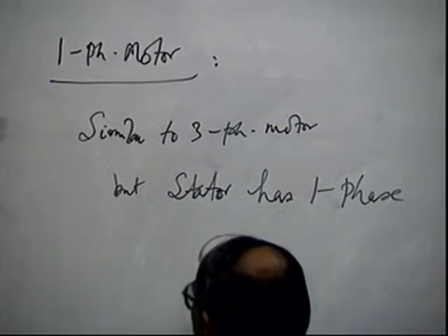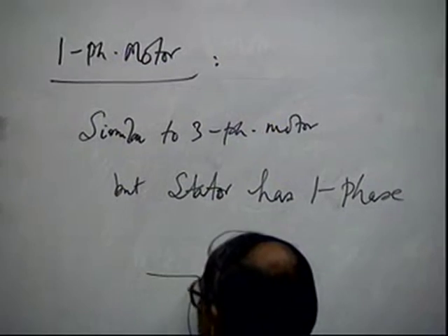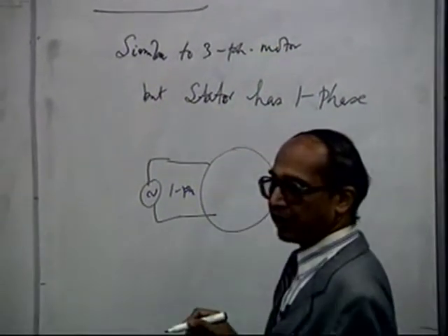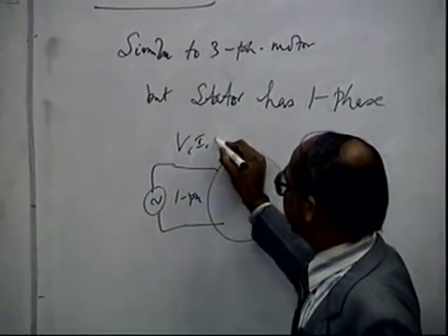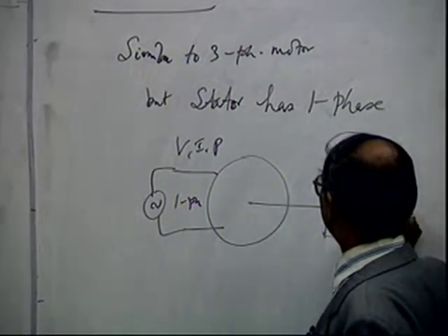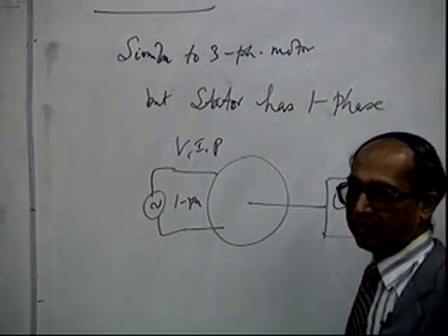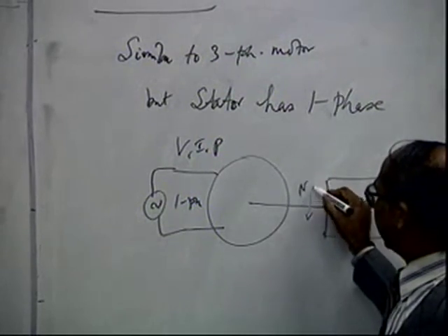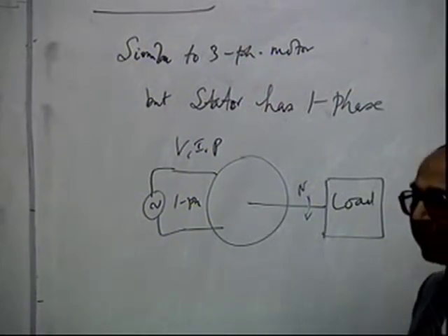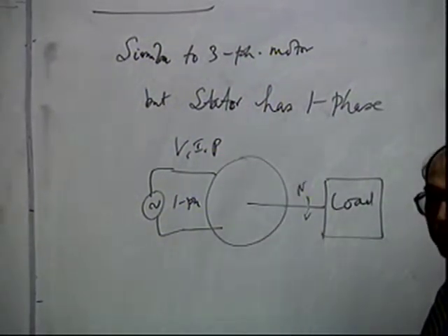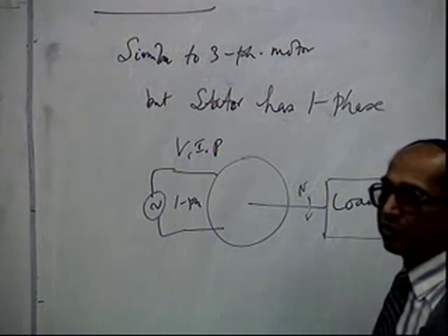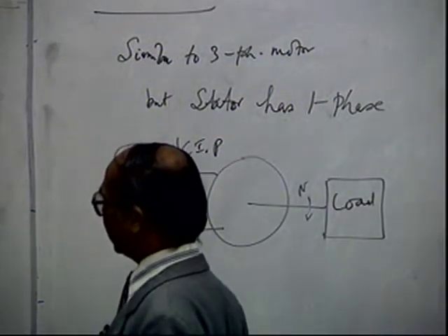Here again you are supplying only a single phase supply, and you measure what is the voltage, current, power under different loads. You conduct at different loads, what will be the characteristics, how the speed, because output is basically speed and torque, input is voltage, current and power. So you will have some idea of the characteristics of a single phase motor, which are again used in large numbers. In fact, single phase induction motors are also the ones which are produced in millions.